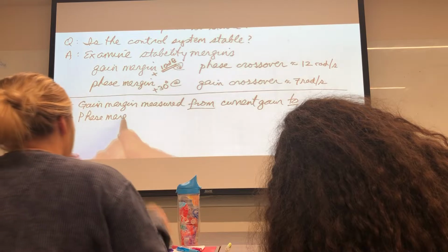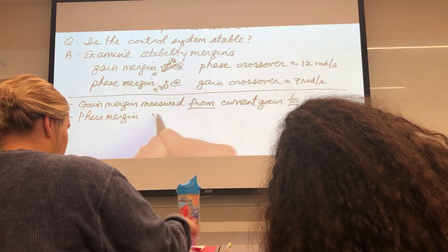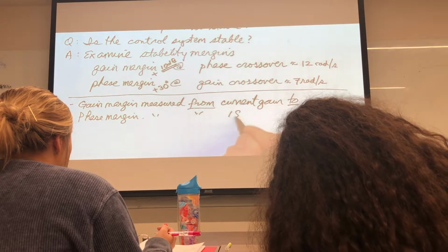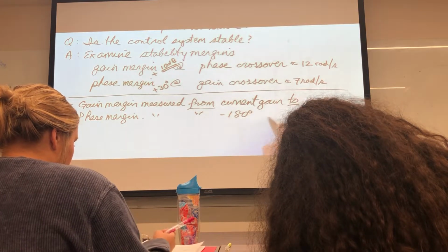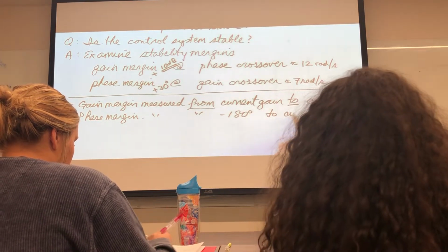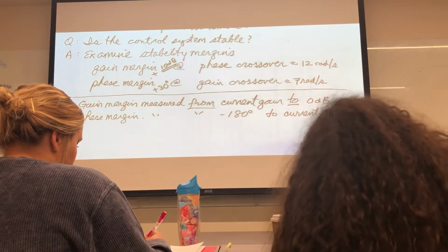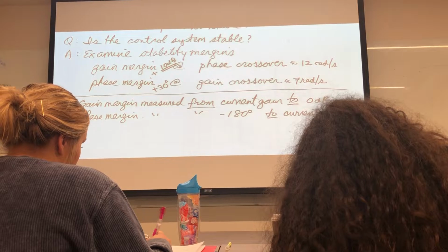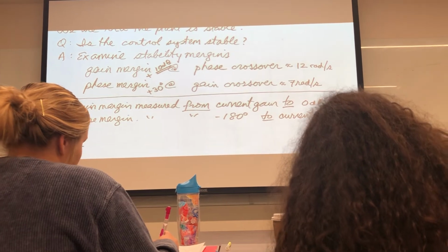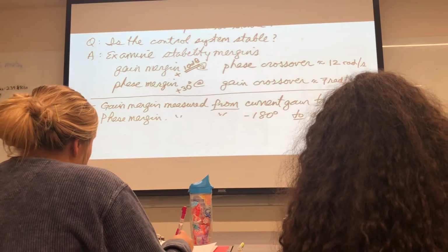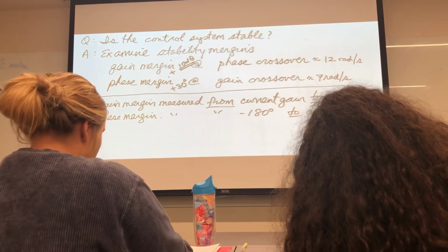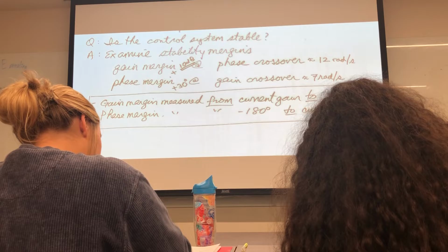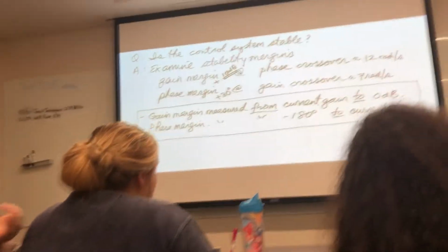Phase margin, by convention, is measured from 180 degrees to the current phase. Okay? So this is important. If you don't remember this, you will get the wrong sign on your margins.